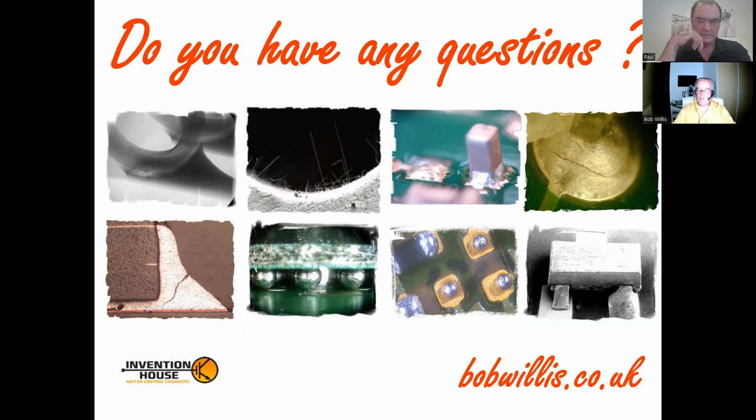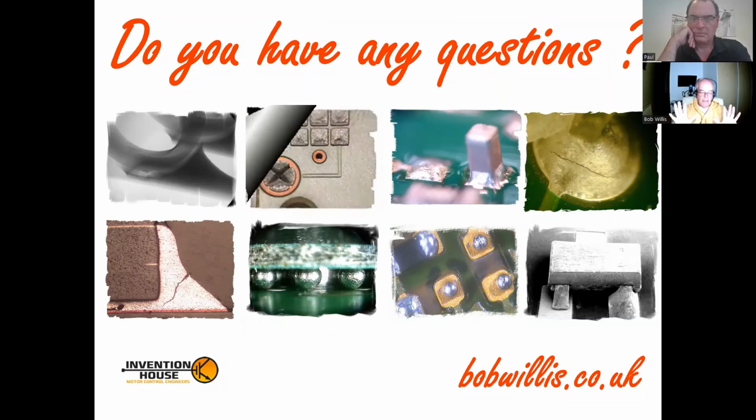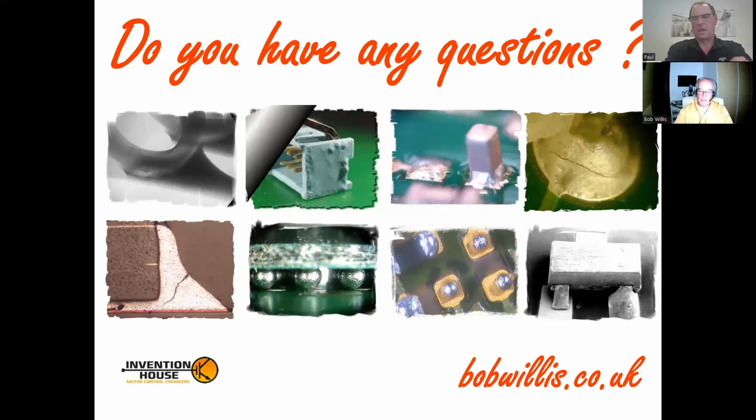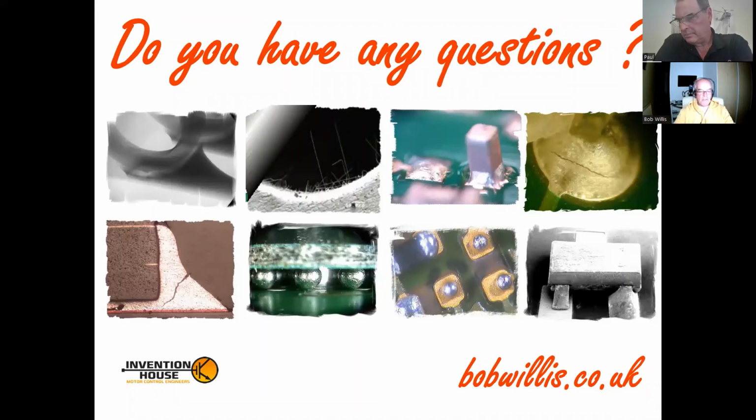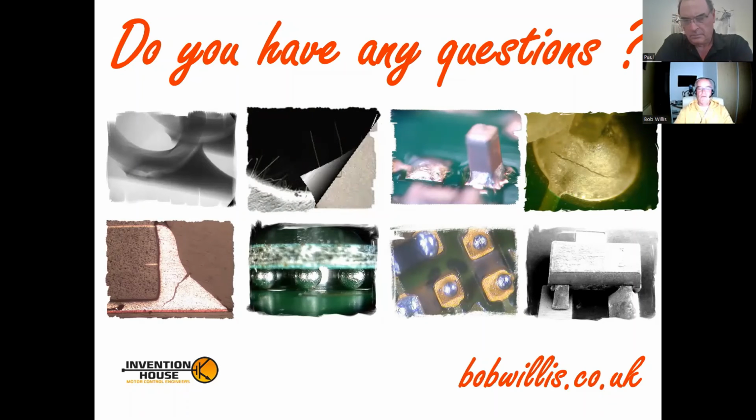We never had them before we had X-ray. So if you don't have X-ray, you won't see them. Anyway, that's been a general comment. But the larger they are, generally speaking, I would say that the less of a problem they are. So I'm not talking about 50% of the solder joint. If they're sort of 10%, 15% by volume of the solder joint, it's not an issue.